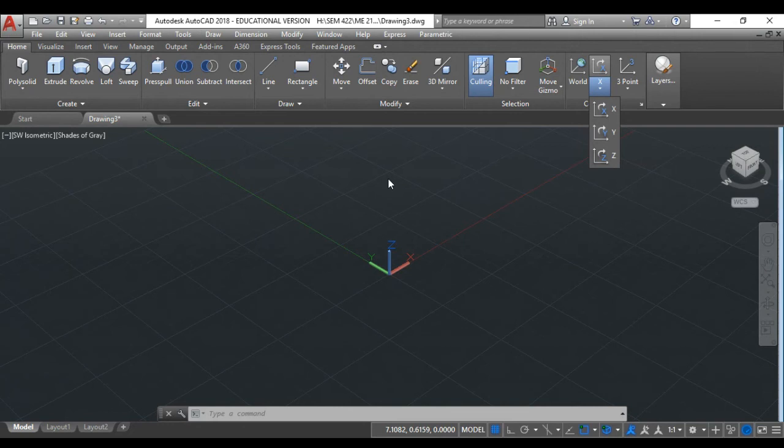Imagine that you are standing at that location, facing your coordinate system. If I need to bring my x-axis to be vertical, you are looking at the coordinates while it's moving clockwise. This means it has to rotate around y in the negative, by adding negative 90.